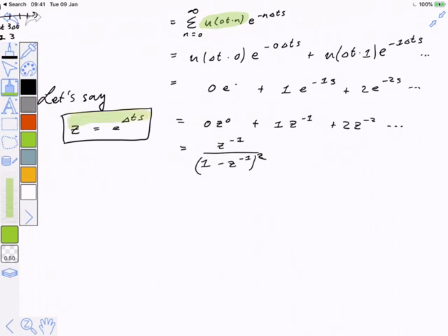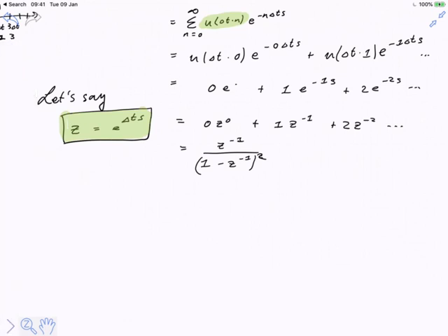If you remember that the Z transform is simply a Laplace transform of that sampled signal with this substitution, you'll be safe. If you allow yourself to imagine that the Z transform is a whole new transform, or is very similar to the Laplace transform, and you can get directly from time to Z, you'll start making mistakes. So what I want you to understand in this lecture is we can do the Laplace transform of sampled signals. We can work through that and do the Z substitution, and that is called taking the Z transform of the sampled signal.